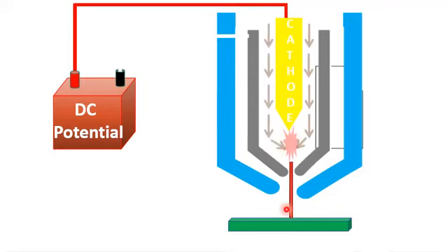So when the stream of the plasma arc from the plasma arc igniter interacts with the surface of the cathode material in the cathodic arc deposition system, it will result in a melt of a very small region of the cathode.